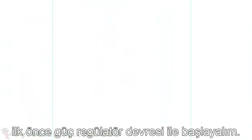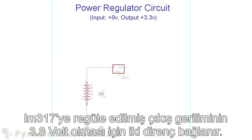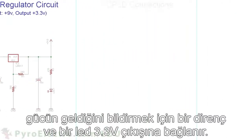Next up, we need to build the hardware schematic. First, we start with the power regulation circuit. This circuit has a 9-volt battery input to an LM317. 2 resistors connect to the LM317 to set its regulated output voltage to 3.3 volt. Then 2 10 microfarad bypass capacitors are added to the input and output of the LM317 to ensure proper current flow. A resistor and LED connect to the 3.3 volt output to notify that power is good.